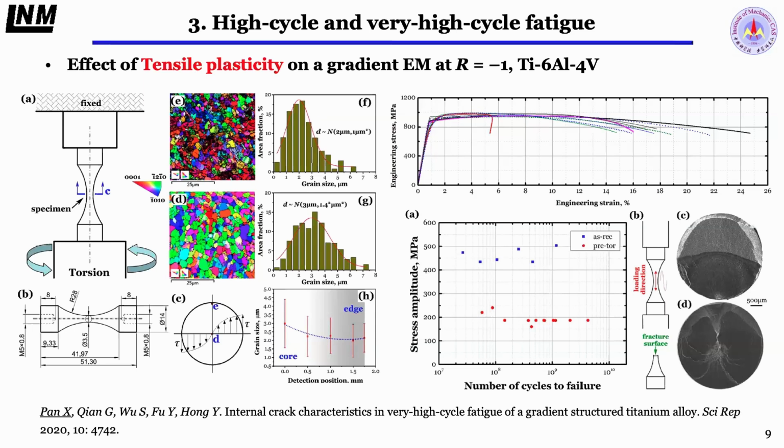This figure shows the surface microstructure and the alpha grain distribution, and in the interior we can see almost flat grains. We find this method can modulate the tensile behavior. The fracture always starts from the surface grain, and then shifts to the specimen interior.